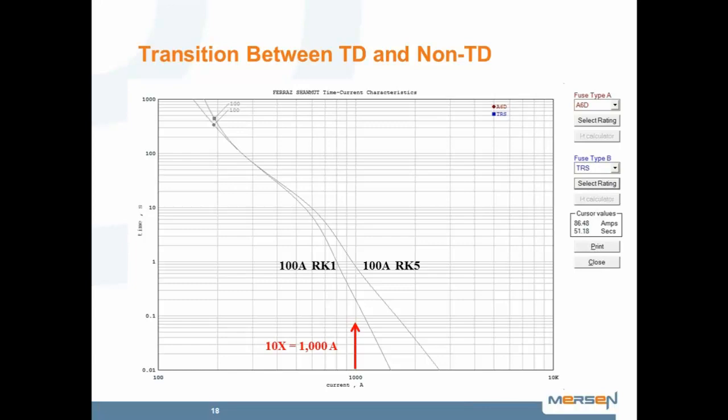So if you have a motor circuit, properly applied fuse of 100 amps, maybe we'll have an inrush of 500 amps, 2, 3, 4, 5. So this is the inrush, and this is the critical part for most motor applications.